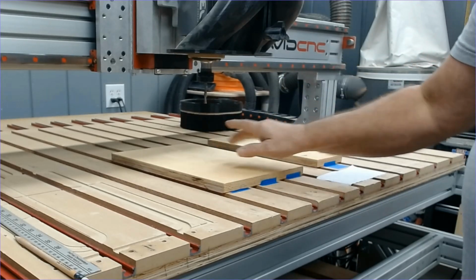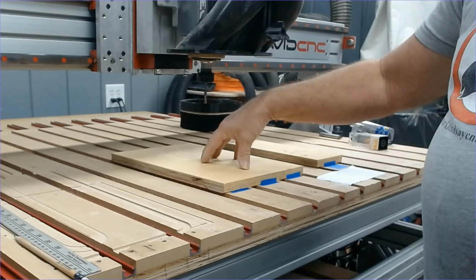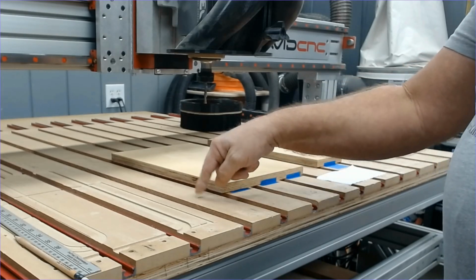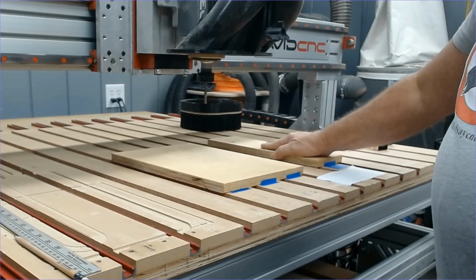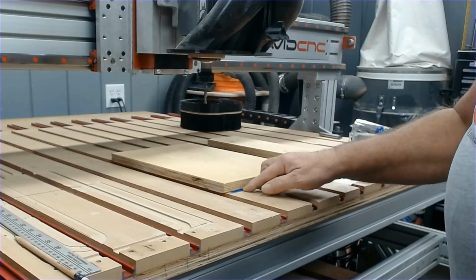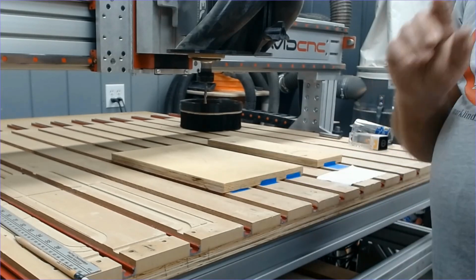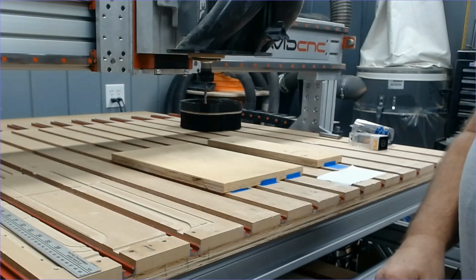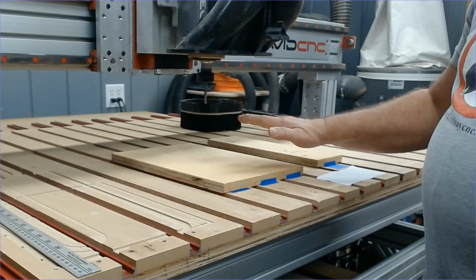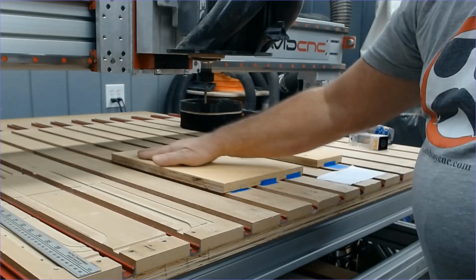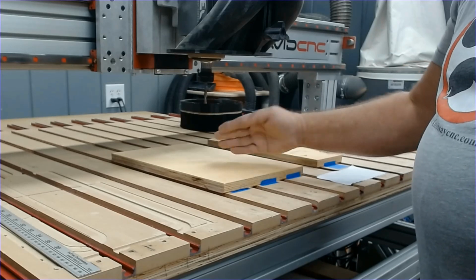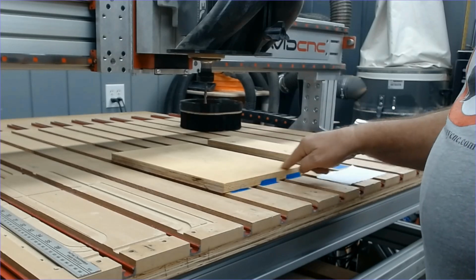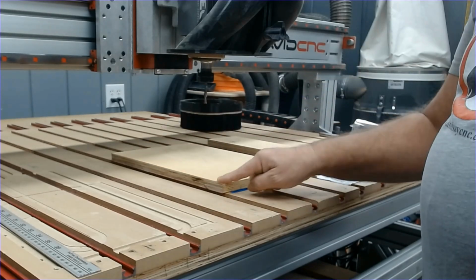All of this is based on the Z0 position on the material surface. If you have your Z0 position set to the machine bed, this is not necessary and the mounting method is not relevant. One thing that I would encourage you to do, however, if you're in a situation where all of this is not going to be machined away, let's say you're going to do a V carving out in this area, but you're not going to be machining out around the borders anywhere.